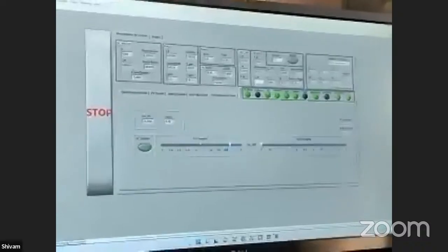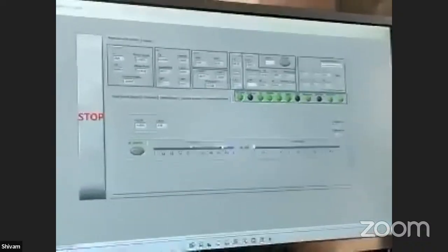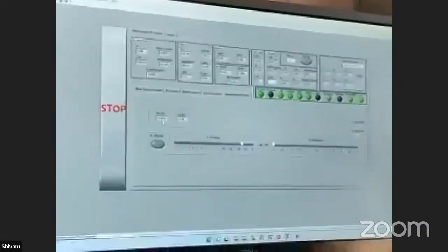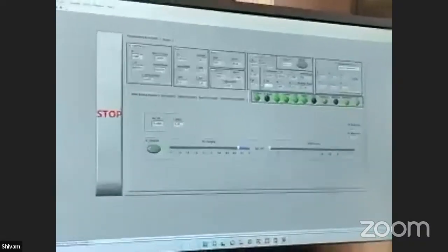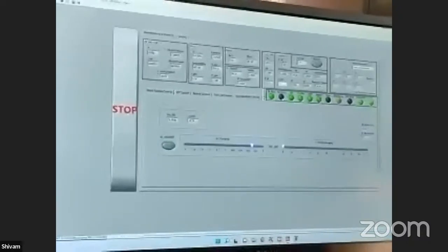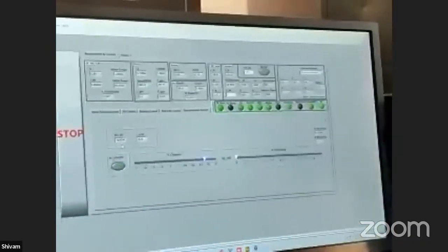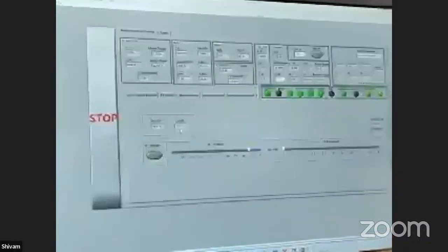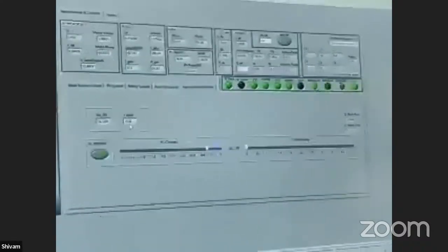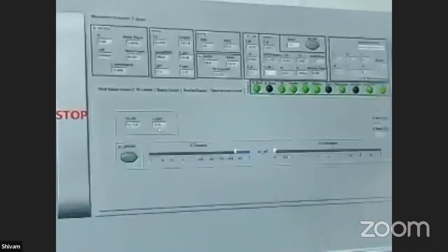That means this supercapacitor started charging. You will slowly see that the voltage is going to build up. Same thing will happen if I start this discharging process. This light will turn from SC buck to SC boost, and I will see that the voltage will increase. Okay? While using this supercapacitor, you have to maintain some voltage on that system. Otherwise, you may face problem operating the supercapacitor.